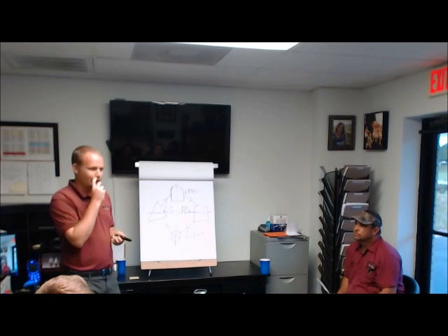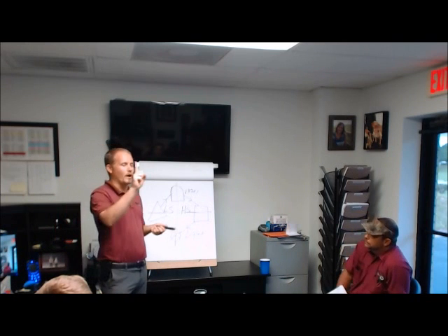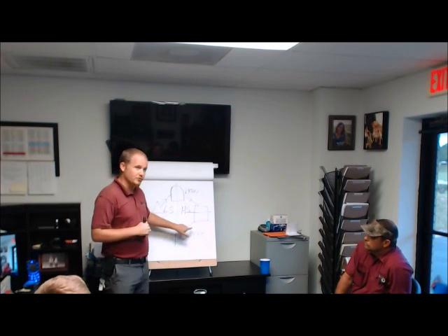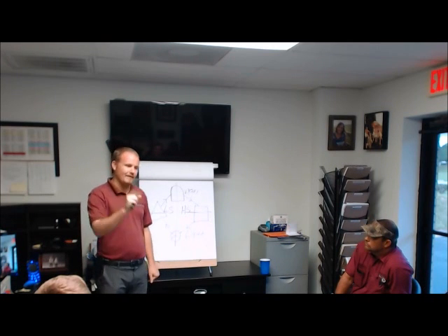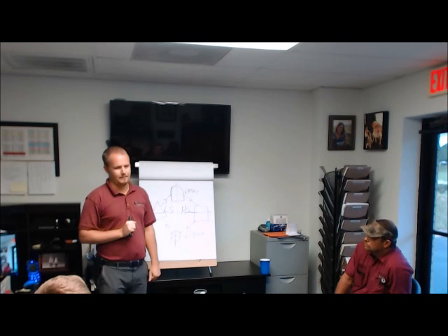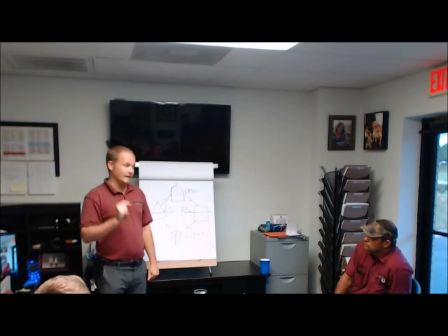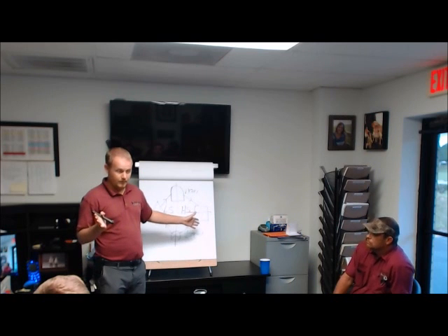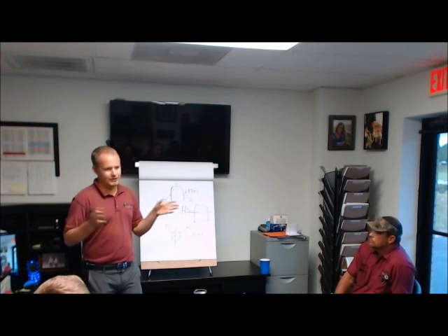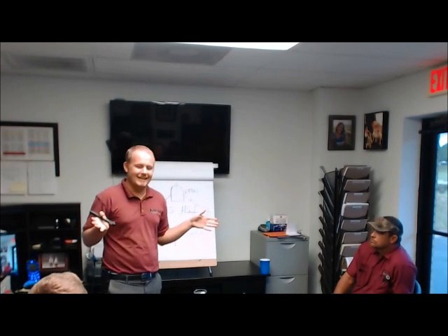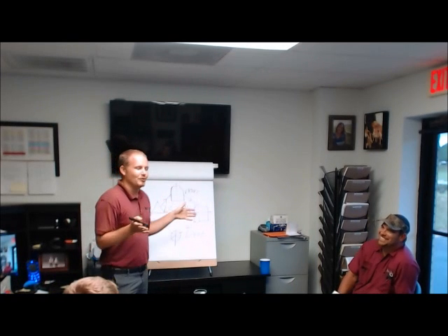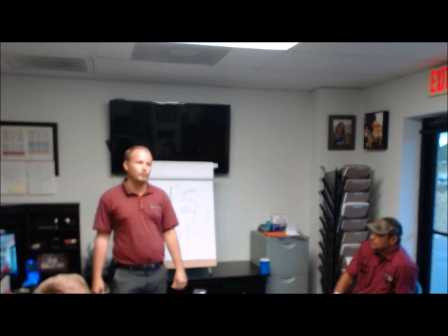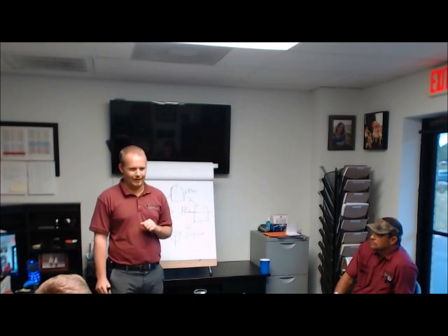Because if you're reading subcool, if you have 1 degree of subcool, meaning that the saturation temperature is reading 98 and it's 97, what does that tell you? You have 1 degree of subcool and the state of the refrigerant here is liquid. It's all liquid. Right? Here's the problem: your gauges aren't that good. Because you could be reading 97 and now, oh yeah, I've got 1 degree of subcool. You may actually have 0 subcool. You may be reading 5 degrees of subcool and have 0 subcool.